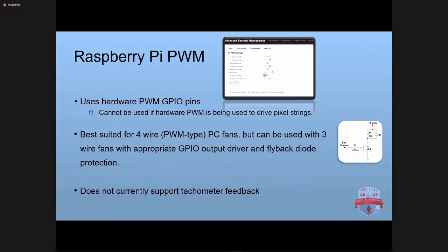And you see the L1 is actually the windings of your fan, and they have a diode in there to prevent any stored energy in that coil, when it's running and shutting off, from getting dumped back into your system by means of what's called a flyback diode or a shunting diode. Basically, that dumps the current back into the coil so it doesn't go into your system. But there's some parts you have to add to make it do that.